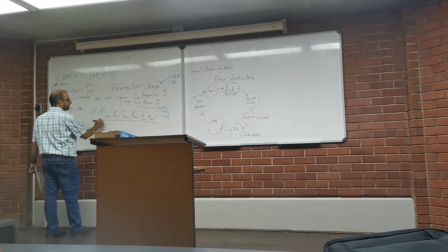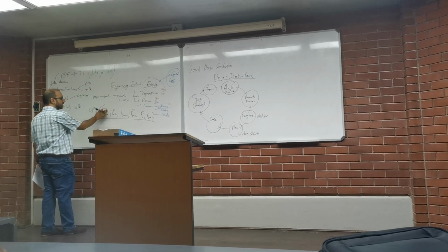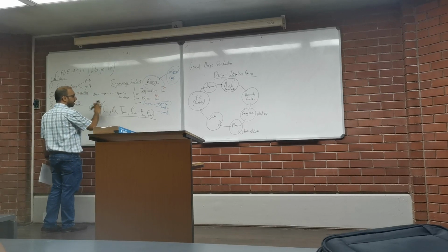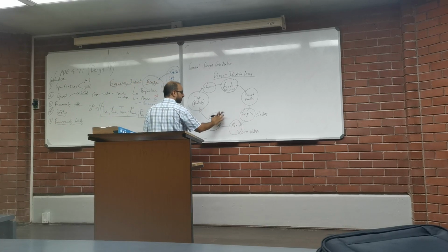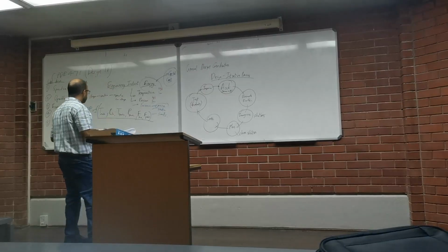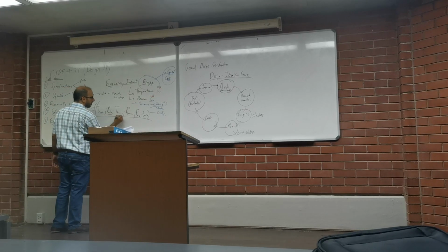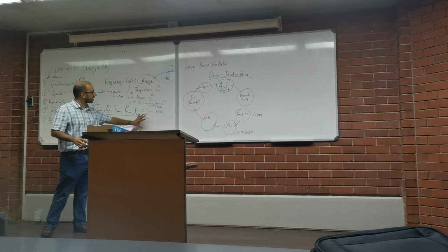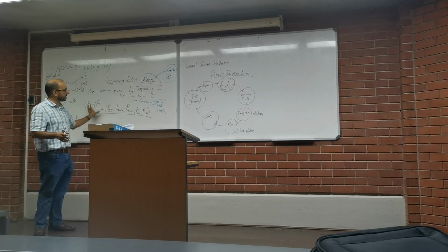Now, there is no set formula for optimizing this because it differs from process to process. It's ultimately handled by you, by trial and error, setting up a whole spreadsheet, a whole simulation. We'll use Aspen, for example, and we'll see whether improving the reactor temperature or pressure, etc., can ultimately bring you the lowest operating costs. So there's a lot of experimentation.